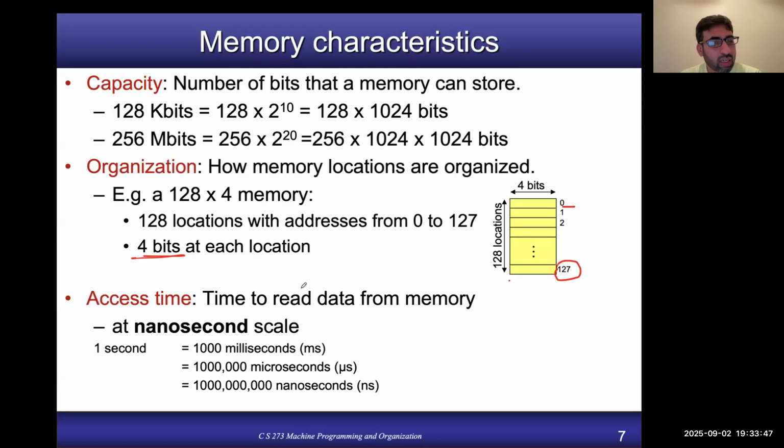However, in case of a write, a processor can say, I just want to write this data in the memory, and if the processor is writing the data, it means the data is already available in the register. So even if it needs to use the same data in the following instruction, it can use it from the register. It doesn't need to wait for the write operation to actually put the data in the memory.